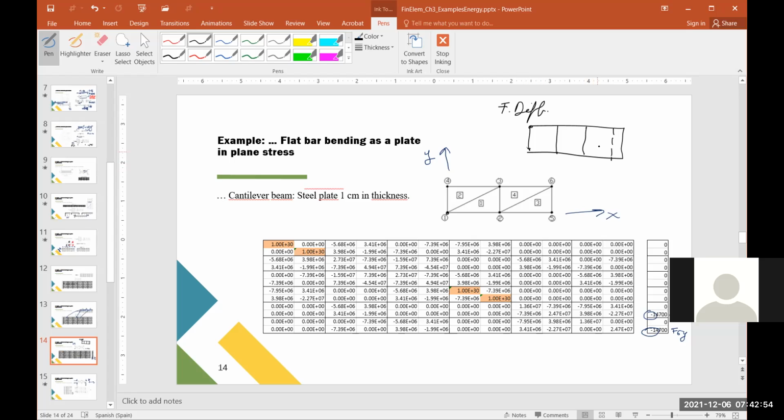For example, if we need to analyze something like this, in finite elements, it's easy. You do something like this and that's it. In finite differences, all you can do is something like this, because your elements have to be square. So we get more flexibility here. That's one of the advantages. But of course, the formulations in some cases are more complex. Of course, nothing is for free.